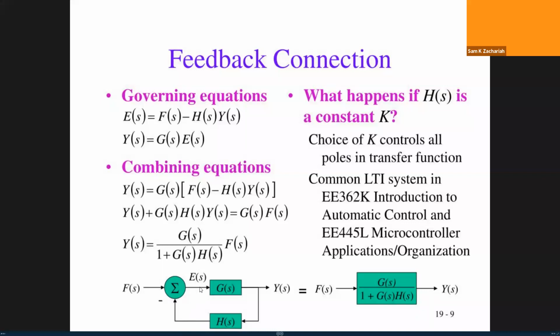Now the output is taken, and in the ideal case of the op-amp, you know that the output impedance of the op-amp is 0. That means whatever value of current you are taking from the output will not affect its transfer function. The op-amp's property will not be affected.